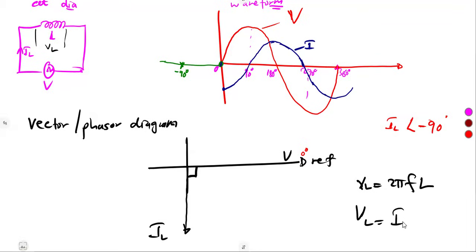So it's just going to be total current times the reactance XL, where our reactance XL is at an angle of 90 degrees. Remember, it's a purely inductive part. The current is the one that lags, that carries a negative, but XL will be positive.